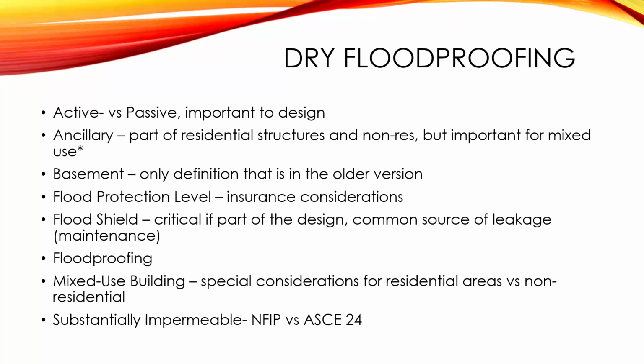So the flood protection level is basically whatever your adopted freeboard is, because there's insurance considerations that you'll only get insurance credit if you have at least 1 foot of freeboard on the dry floodproofing protection level. So flood shield, this is a very common part of a dry floodproofing design, but also a common source of leakage and failure of that system.